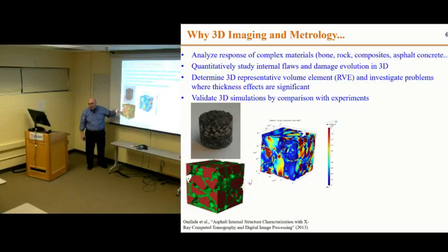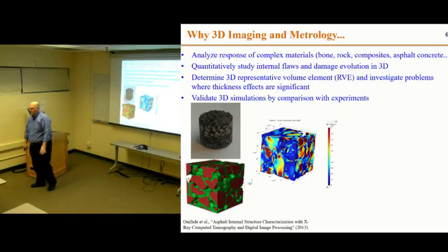I can do that with an optical microscope or even with an SEM, but it's very time consuming to do with a tomograph. We've done it. We've done a scan here, a scan there, and a scan there, and tried to join them. But that's like 5 hours worth of experimentation, not the easiest solution, but that is another possibility. I think for me, the biggest challenge is that as you increase volume fraction, it is more difficult to make quantitative strain measurements. And a lot of the materials that we use have high volume fractions, above 50%.